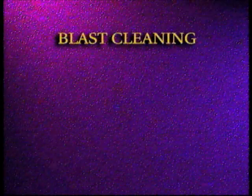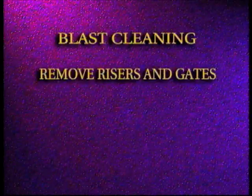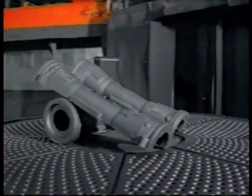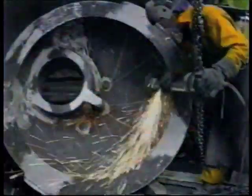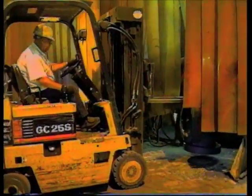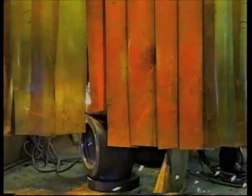This includes blast cleaning, removal of risers and gates, heat treatment, welding, and machining. Blast cleaning is used at various stages in the finishing to remove adhering sand, oxide scale, and produce a uniform matte finish. Risers and gates used to make the quality castings must be removed. Since most cast alloys are weldable, welding may be used if required.